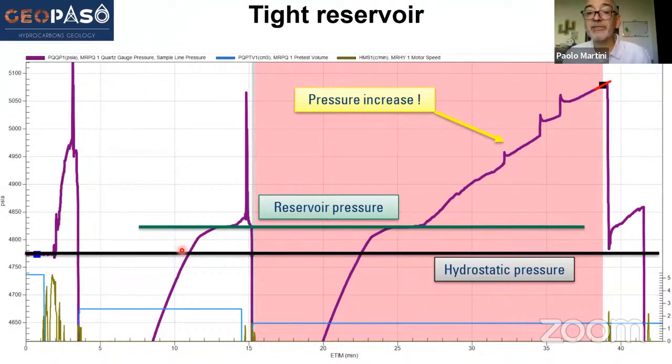So it's possible that this trapped pressure is more than this 5,080 or 5,079 psi. The difference would be even more than the 300 psi we see here. And it's a bit unlikely that you manage to drill a well with such a high underbalance without realizing it.